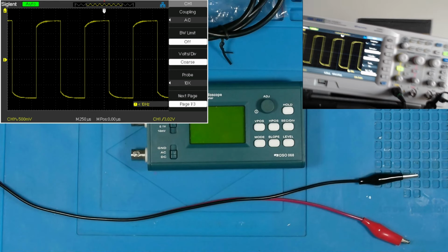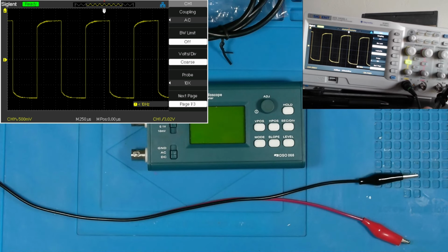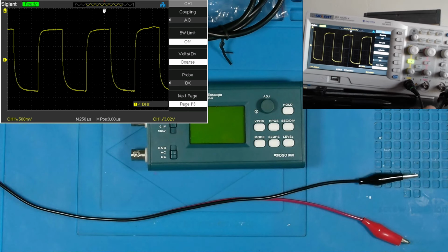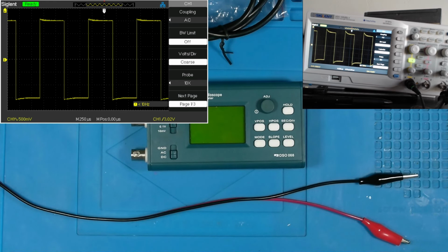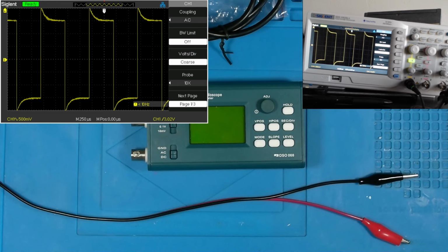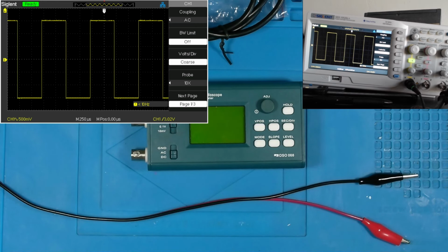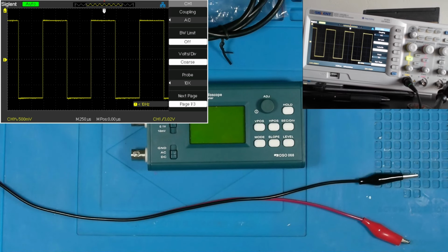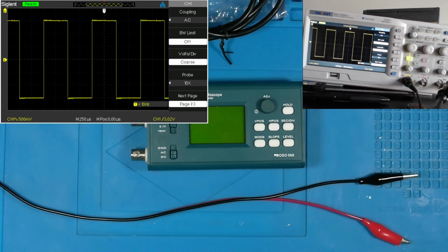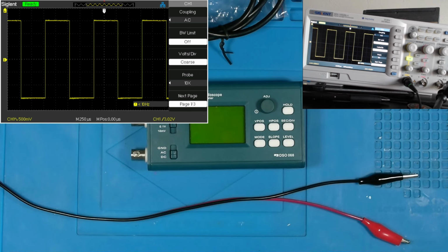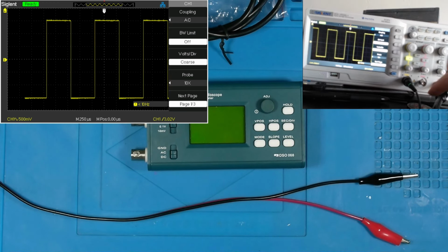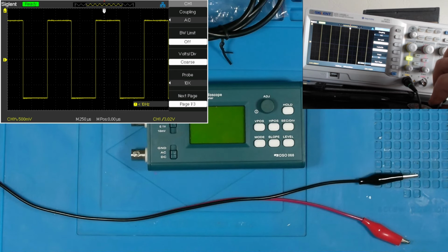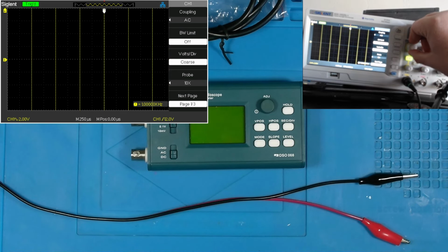All right, let's compensate again. There we go. You see those changes? This is counterclockwise. This is clockwise. And now we've compensated our probe correctly, with that little fine adjustment to have a nice waveform. Switch it back to 1 by, and we'll bring this down.